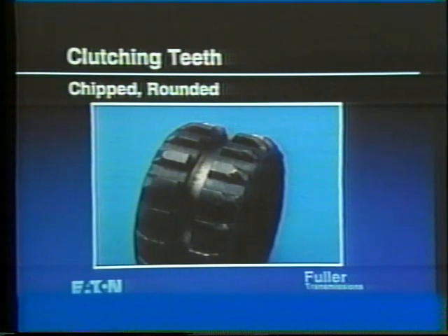However, chipped or severely rounded clutching teeth will help create a slip-out problem. This wear can be caused by improper clutching and shifting techniques. Parts as badly worn as this should be replaced.